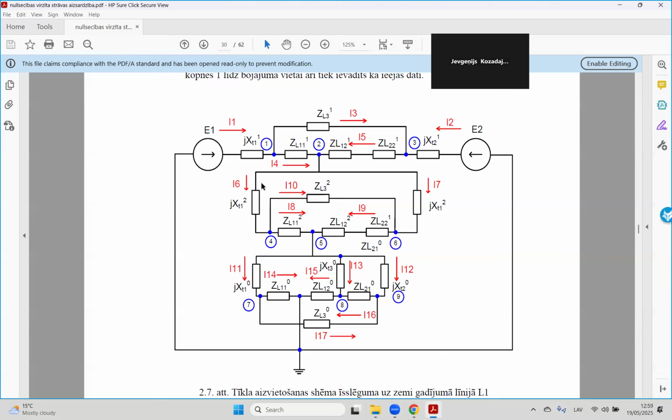So we connect the positive sequence fault point to the negative sequence neutral wire, the negative sequence fault location to the zero sequence neutral wire, and the zero sequence fault location to the positive sequence neutral wire and ground.